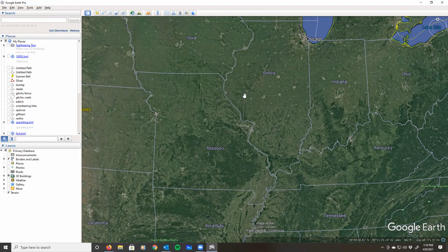So this is something that's established by NGS in the process. Basically, by defining a certain latitude and longitude on a meridian, and establishing a scale factor at that point or along that meridian, it makes a mathematical model that can be worked with to figure out the scale factors in other locations.